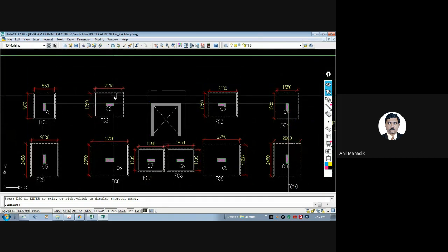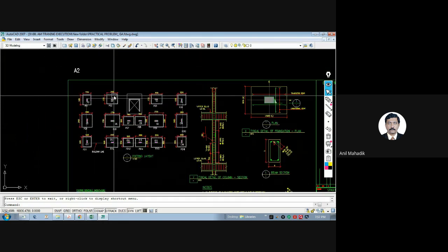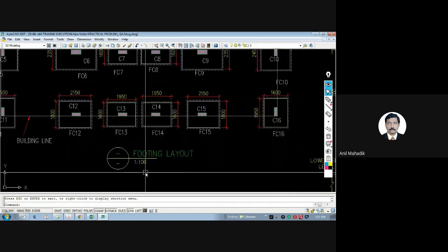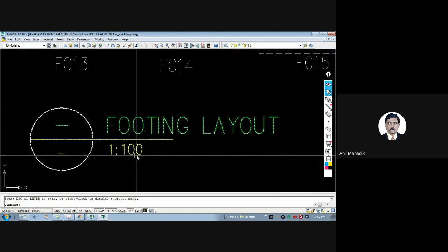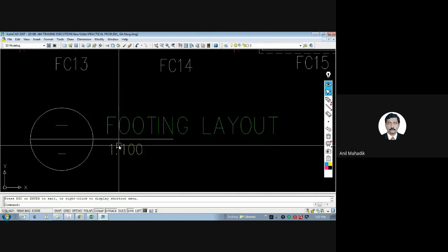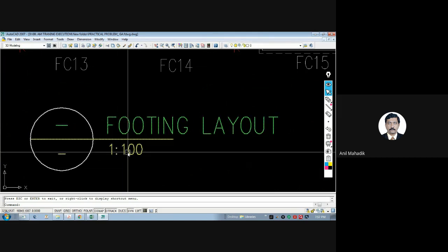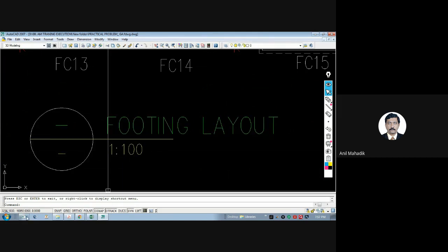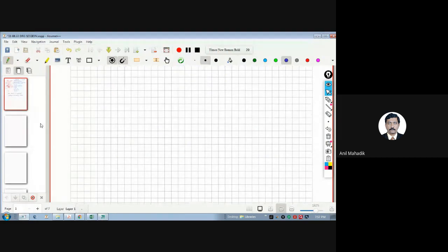But whenever you print, it cannot fit within the print. And that's why we give the scale. Do you know why we give the scale as 1:100 or 1:50? Because the actual size cannot fit within the drawing. That's why we are reducing it, or dividing by the scale. So how do we prepare the drawing, for example? It's an important topic actually.